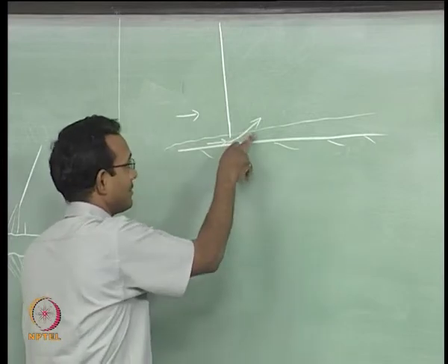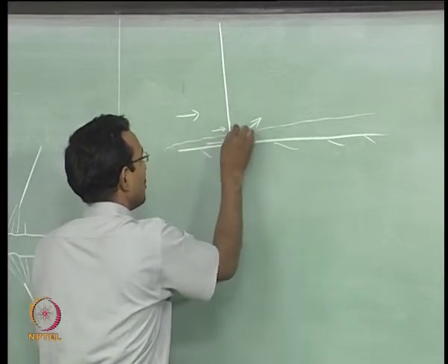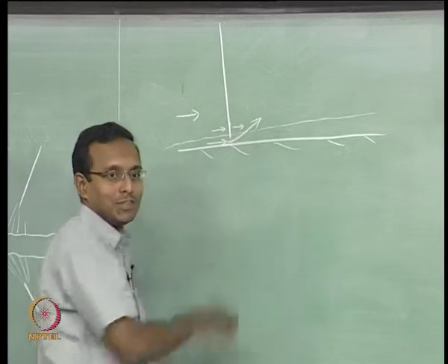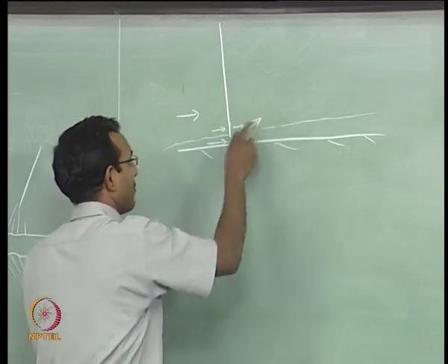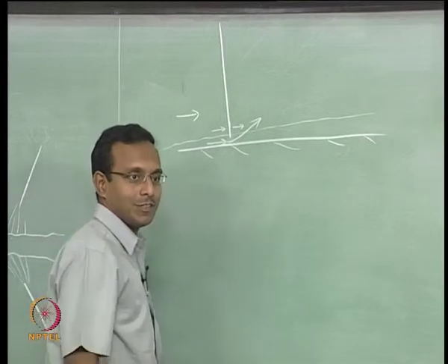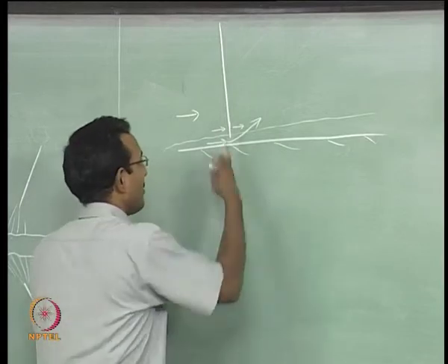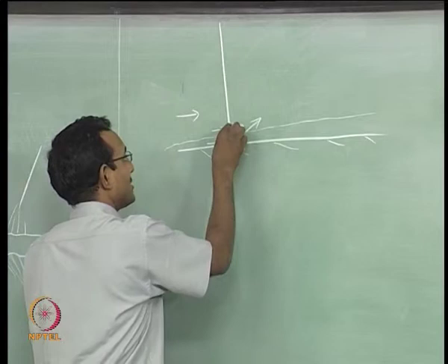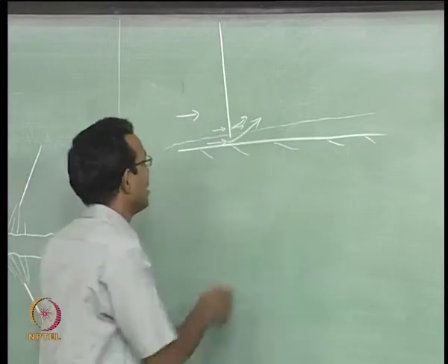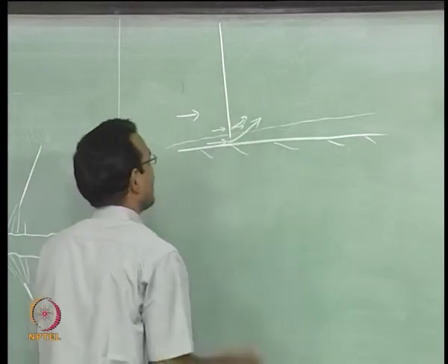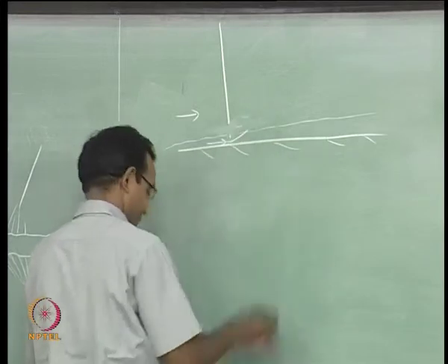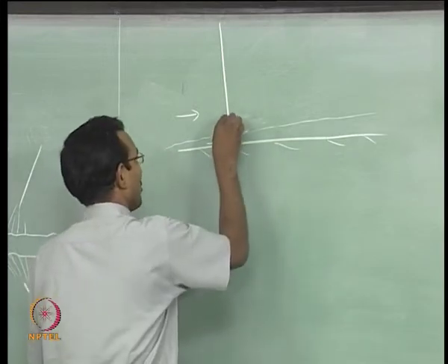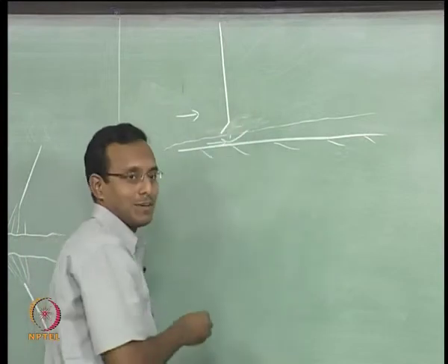But when this happens, the flow that is supposed to go straight will now go and crash into the next flow streamline. Right? This streamline is coming up and this streamline is going straight. So, there is a problem there. What will happen? There should be an oblique shock to adjust this flow to go like this. So, this normal shock is no more a normal shock. I am talking again unsteady problem. I am giving you how a normal shock boundary layer interaction happens.